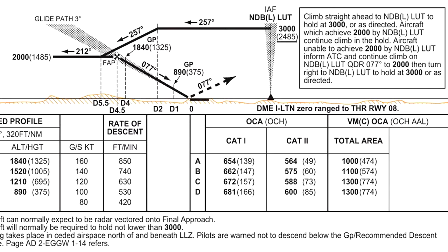Wingspan is not more than 60 metres, and the vertical distance between wheels and glide path is no more than 6 metres. Missed approach climb gradient is 2.5%, and the glide path angle is a minimum of 2.5 degrees, has an optimum of 3 degrees, and a maximum of 3.5 degrees.